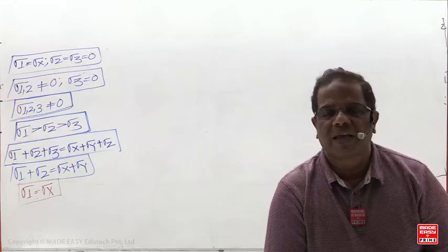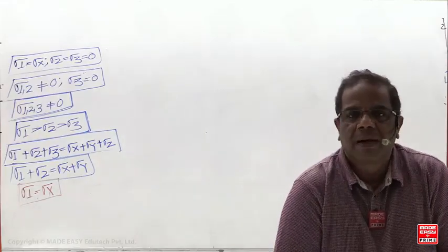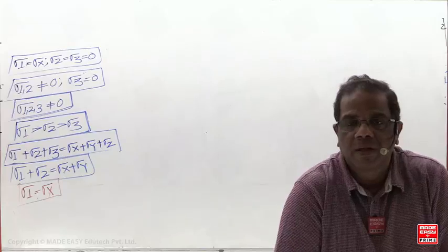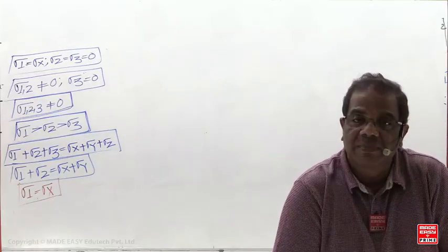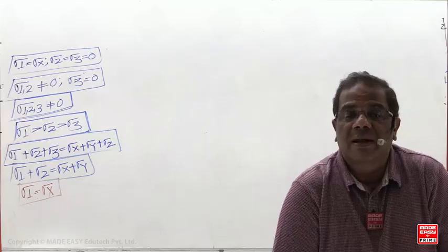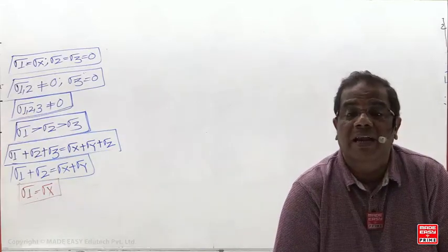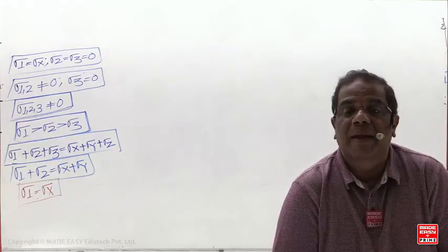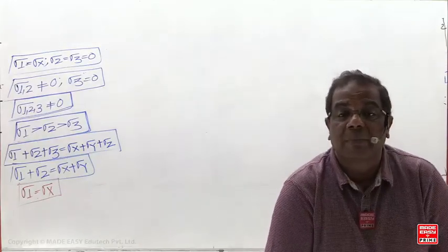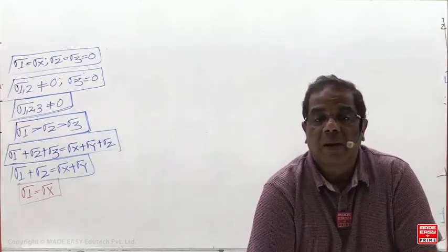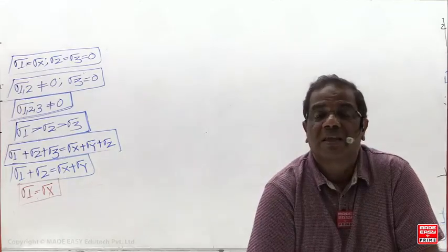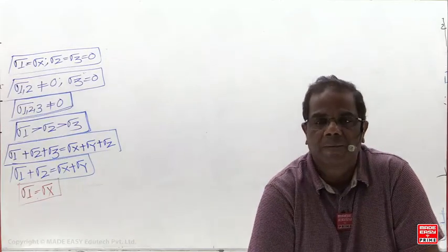On tau max plane, shear stress is maximum, but normal stress is equal to sigma x plus sigma y by 2. So when that normal stress becomes 0, that is when sigma x plus sigma y is 0, on that plane you are getting only shear stress. Then that plane is called the plane of pure shear stress. So tau max plane will become the plane of pure shear stress only when sigma x plus sigma y is 0.